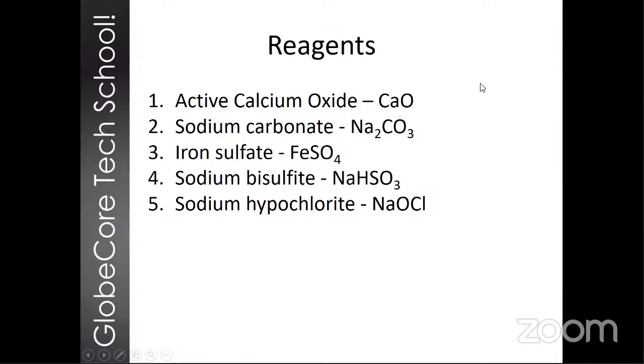So on the reagents that we use in the AVS processes, the chemicals that we use depend on the type, nature, and volume, the amount of wastewater. It depends on the concentration of the pollutants and the treatment methods used. So in this case, to neutralize acids, alkali, and for precipitation of heavy metals in the form of hydroxides, we use lime milk, calcium oxide, soda ash, and other reagents, preferably lime milk, since it contributes to the formation of a well-settling, easily settling sediment.